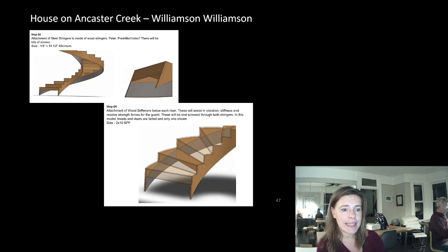Remember, thin steel in bending is actually governed by the buckling of the compression side. So you remember, steel isn't great in compression because it likes to buckle if it's thin. And in bending, the top usually is in compression, so it tends to buckle. It's great in tension.